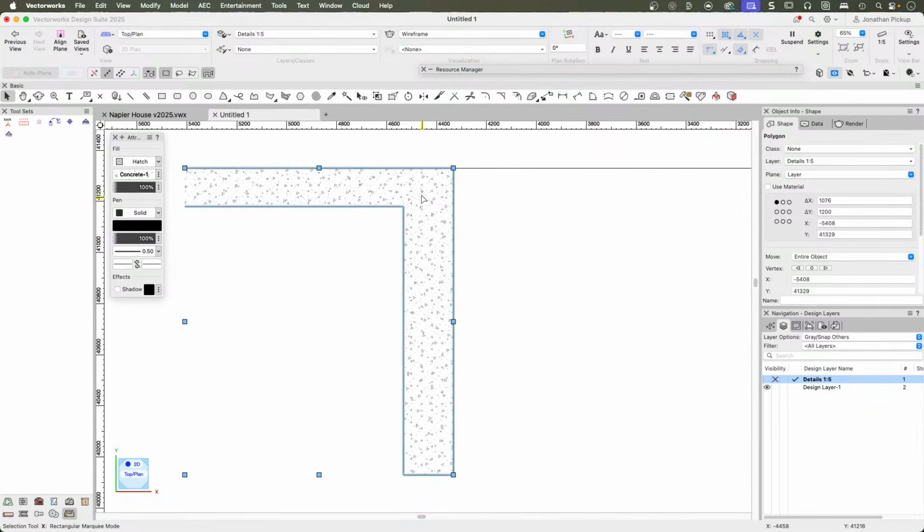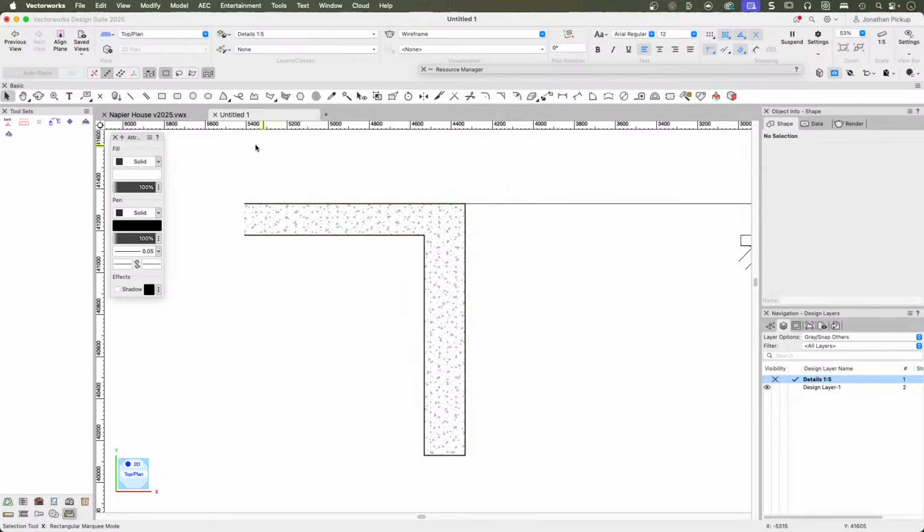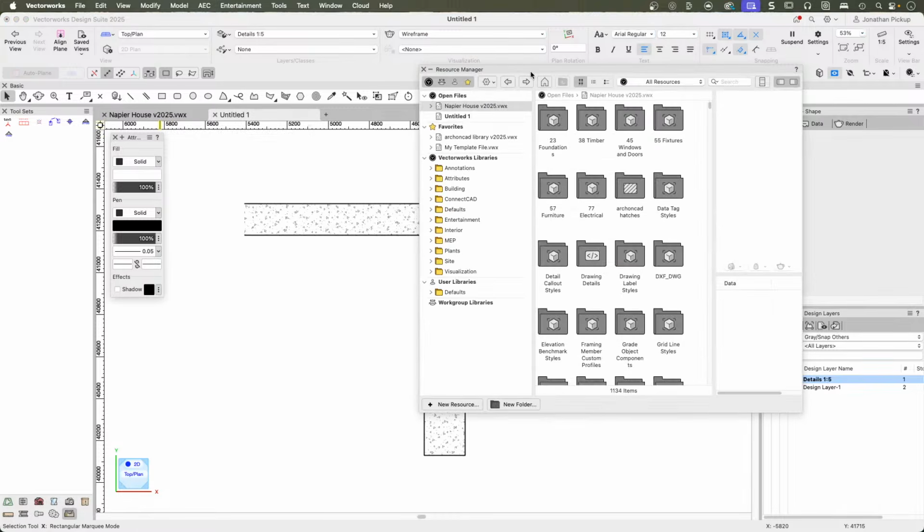The reason for that is because details are internationally understandable if you use the right graphics. There is an international way of thinking about details with the graphics that we use. We put cross-hatching in timber to represent solid, continuous timber. We put a single line to represent discontinuous or blocking timber. So there are some things that are just always common that we use. Now that works pretty well, but you can make it improved.